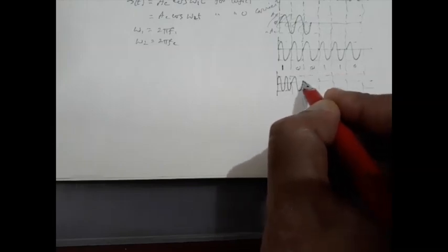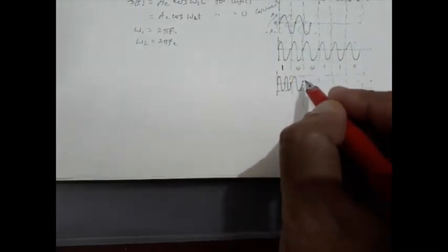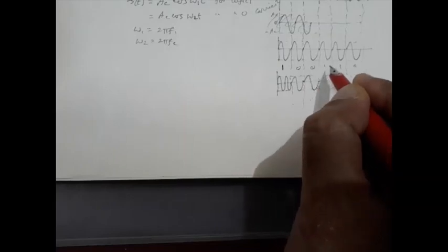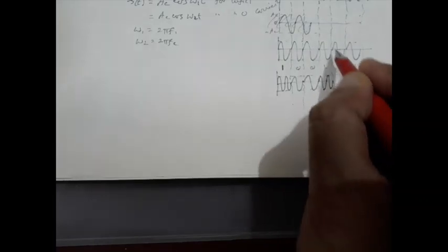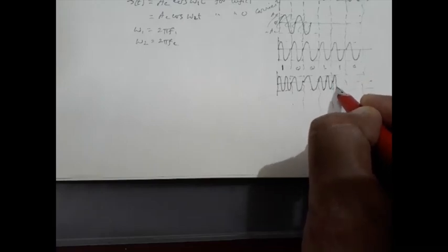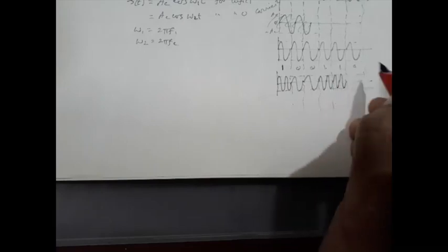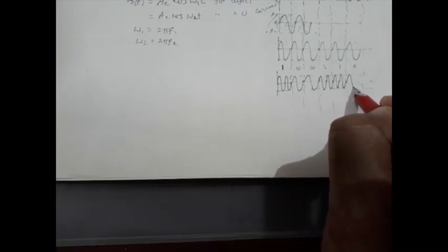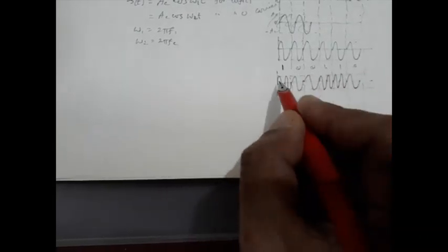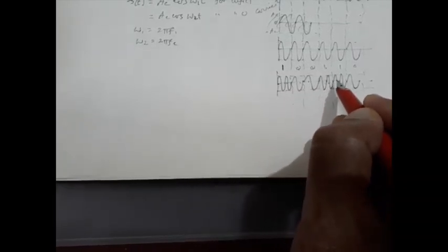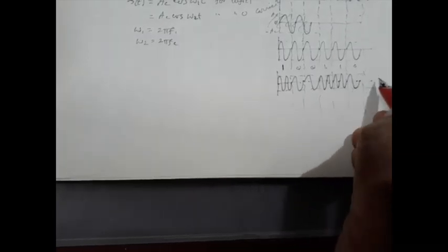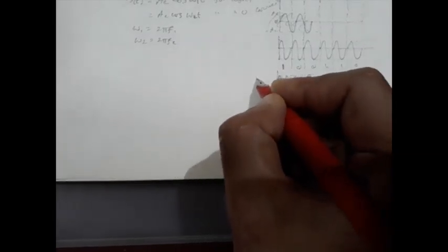Then we have again logic 0, so this carrier. Then we have 1, means this carrier. Again we have 1, so high frequency carrier. Then we have 0, means low frequency carrier, like this. So for this data, the waveform will look like this: higher frequency, lower frequency, lower frequency, then higher frequency, lower frequency. So in this way, the waveform will change. Binary FSK signal.